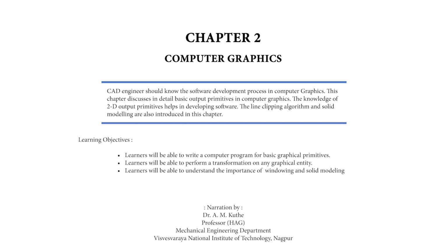Para 2.11.1 Wireframe model. A wireframe model of an object is the simplest geometric model that can be used to represent the object mathematically on the computer. It is sometimes referred to as a stick figure or an edge representation of the object. It can be imagined that a wire is bent to follow the edges of the object to generate the model, hence it is called a wireframe model. A wireframe model consists of points, lines, areas, circles, conics, curves, etc. Wireframe modeling is considered as a natural extension of the traditional method of charting.